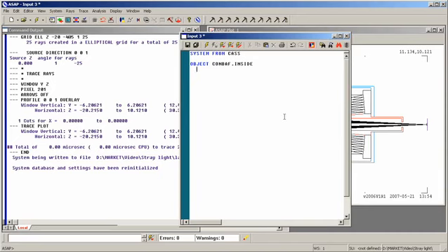The easiest way to do that in ASAP is to enter the scatter command. Scatter random. I enter the diffuse reflectance, which for a diffuse black surface is typically around 5%, or 0.05, and I tell ASAP how many rays I'd like to scatter. That is to say, for every incident ray on the interior of the baffle, how many scattered rays shall I generate to actually propagate to the detector? For simplicity, I'm going to scatter 10,000 rays. For every incident ray, I'll scatter 10,000 additional rays to the detector. At this point, I'm done. I can issue the command return, which says I'm all done with this object.